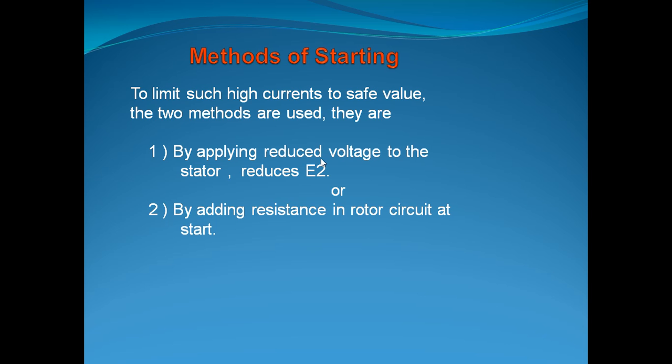So, by applying reduced voltage to the stator, or by adding resistance in the rotor circuit at starting.